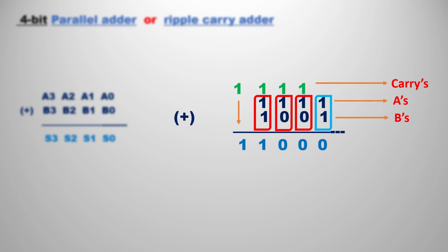With this you can observe there are mainly four columns. Four columns means we can simply call it a 4-bit parallel adder. The final carry that we get is 1, which I am dragging down as the final output 1, and the output is 1 1 0 0.